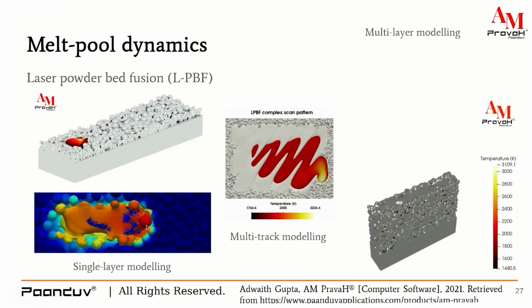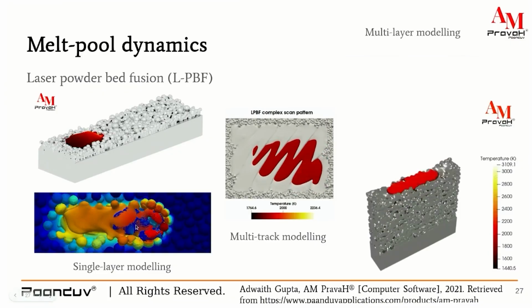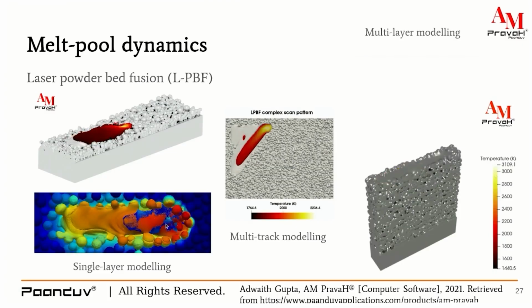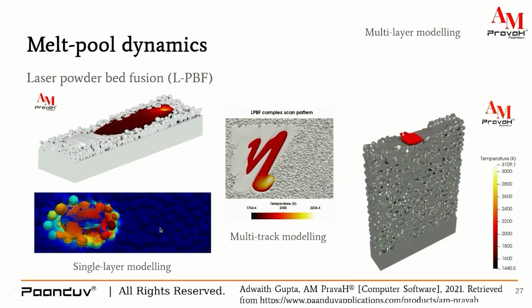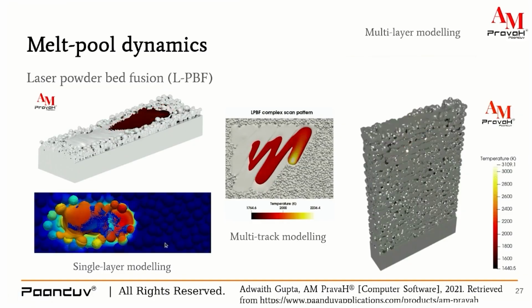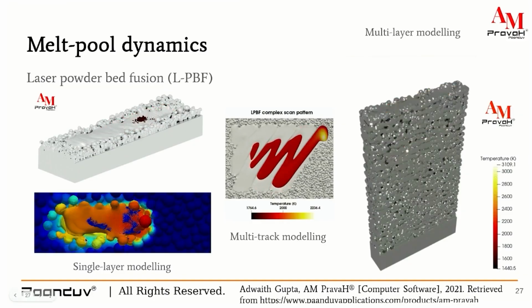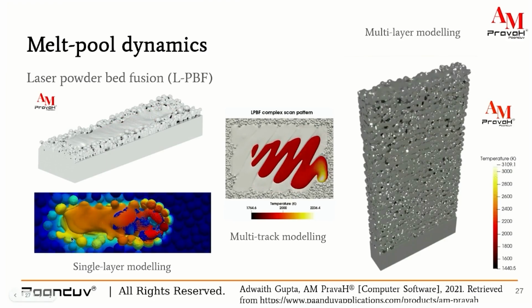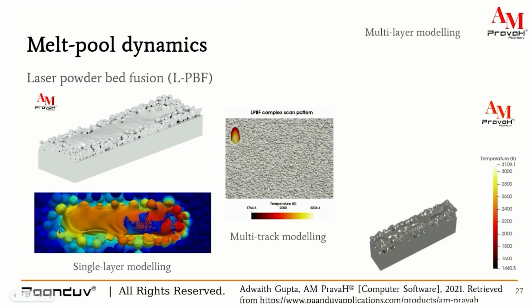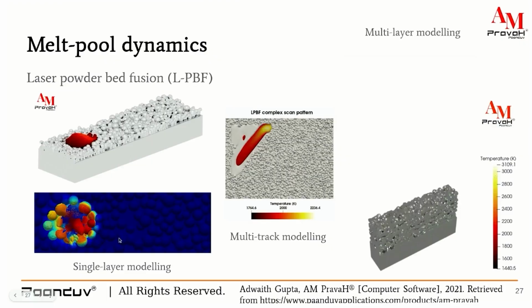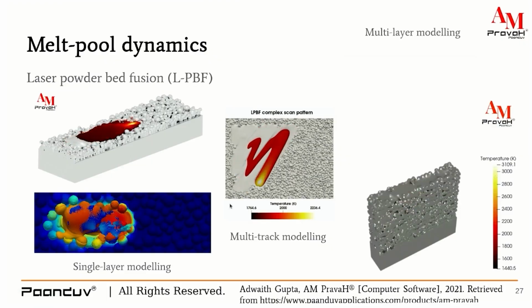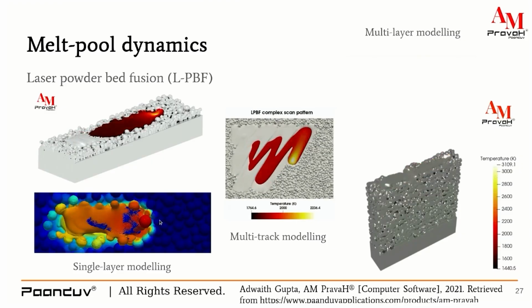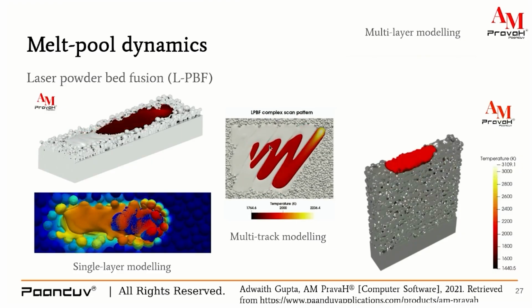There is an example that we have validated with the experimental results. This is a Nature article publication that we have taken for a bare aluminum plate. The laser power here is 500 watt. The scanning speed is 1.2 meter per second, and the spot diameter is 50 micrometer. And you can see at the beginning of the melt pool itself, the keyhole is unstable.